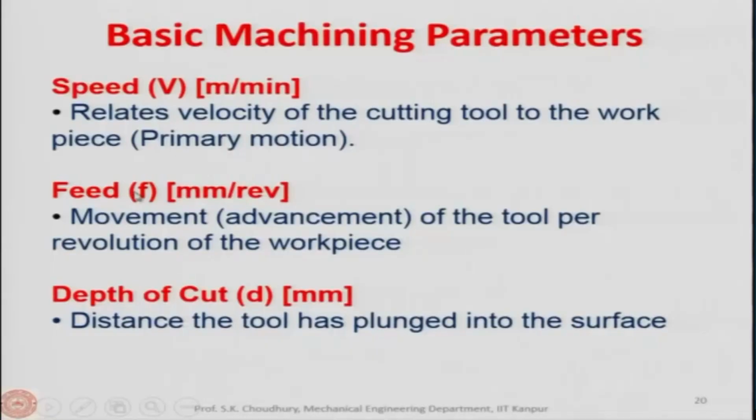It is in the case of the planing. Okay. So, it is given in the unit of meter per minute, as I said. Now, the feed is the movement in millimeter of the tool, in one revolution of the workpiece. Movement is the advancement of the tool per revolution of the workpiece. How much the tool has advanced to the workpiece material. Okay. Now, the depth of cut, it is in millimeter, it is the distance the tool has plunged into the